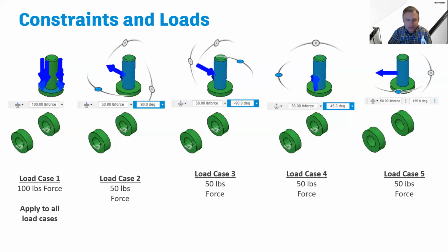Now, the one that I selected here, by the way, this is more of an industrial one, but same concept, okay? Now, let me introduce what's referred to as load cases. So you'll see here that I have 5 load cases selected. Now, these load cases, think of these as different points in time, okay? So the first load case is just stationary. I have 100 pounds pressing down on the frame.